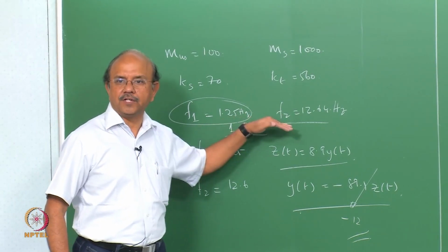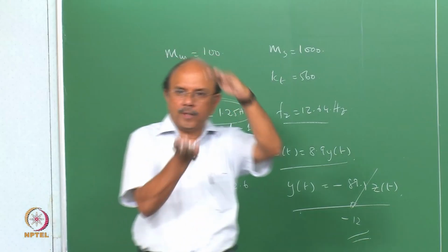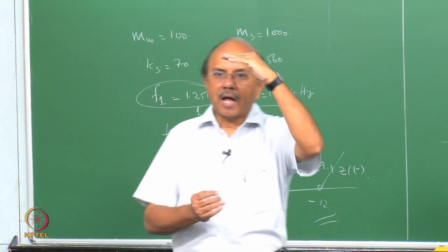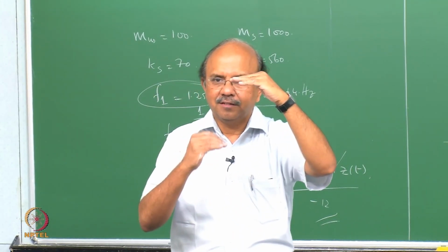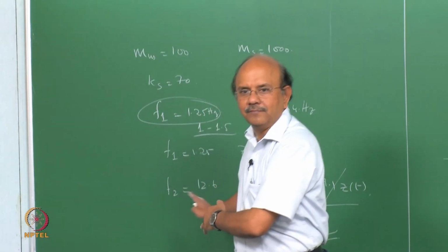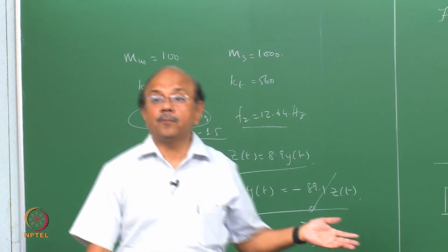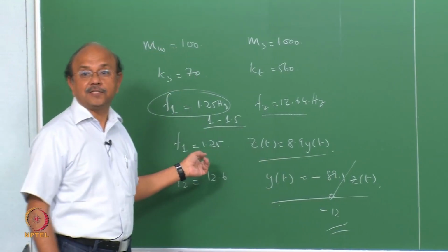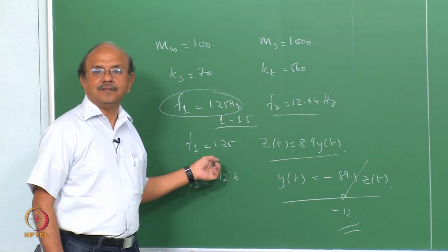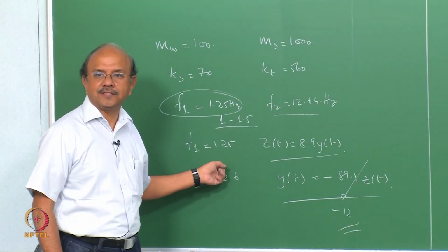At that frequency of oscillation, what is the movement of the unsprung mass and the sprung mass, that's what we are expressing here. But it will also depend on input frequency, right? No. We are talking about natural, right answer is equal to 0. This is the free vibration case.